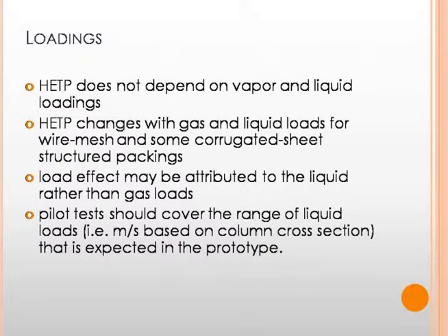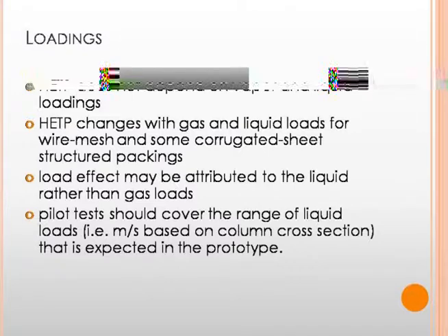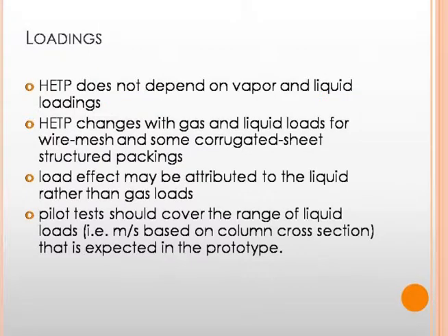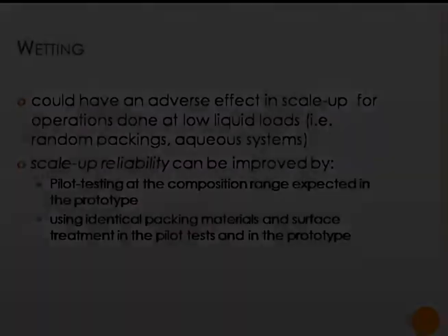The third consideration is loadings. Generally, HETP does not depend on vapor and liquid loadings. However, for certain wire mesh and some corrugated sheet structured packings, HETP changes with gas and liquid loads. The load effect may be attributed to liquid rather than the gas loads. As such, pilot tests should cover the range of liquid loads that is expected in the prototype.